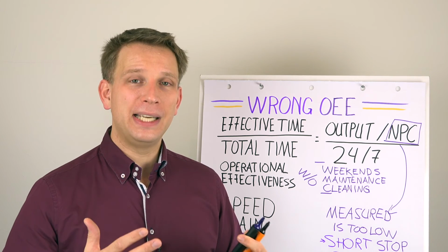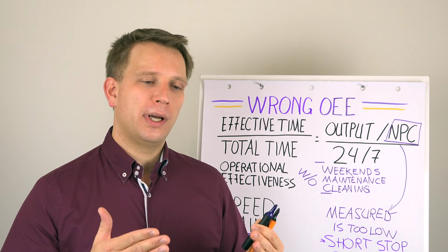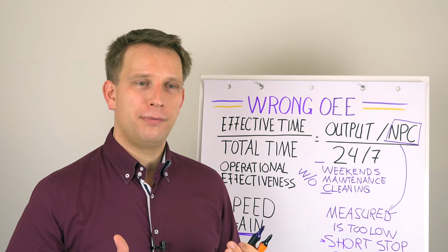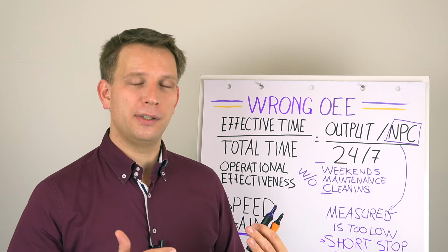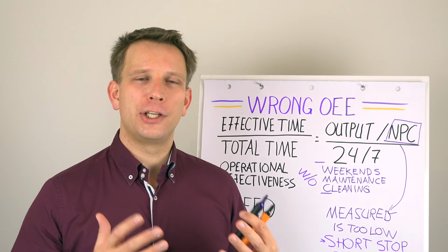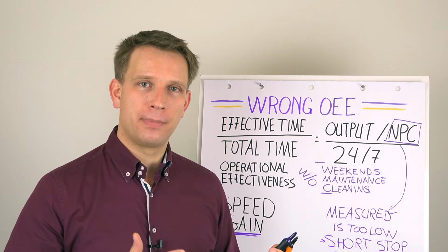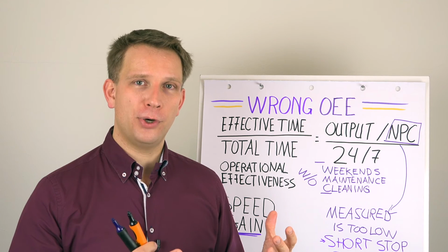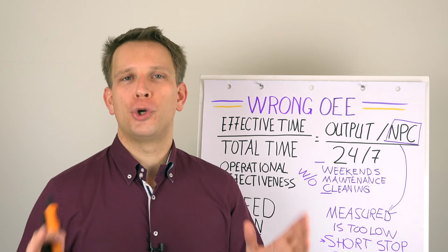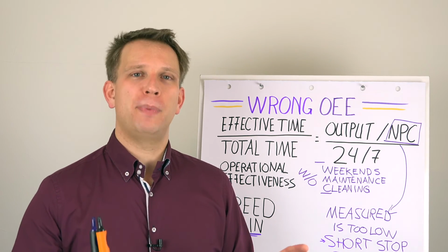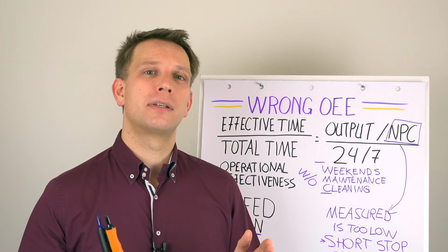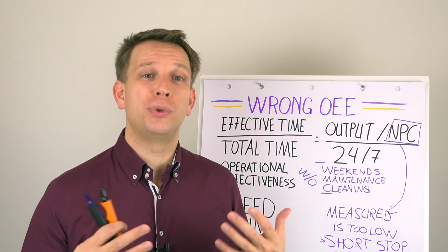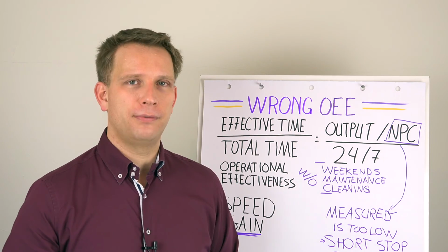The only thing that it really tells you is that when you are today under 50, and especially seriously under 50, then you have a problem that you can fix. And when you are at 55 or so, you are probably at your current best. So don't spend too much time on today's 55 OEE, so today's 45% of time loss.